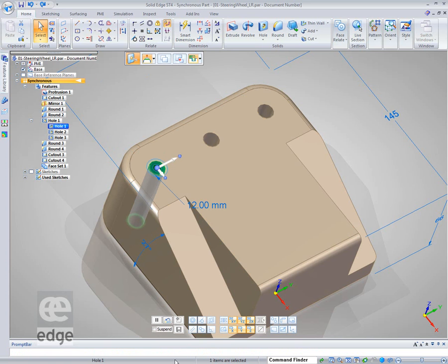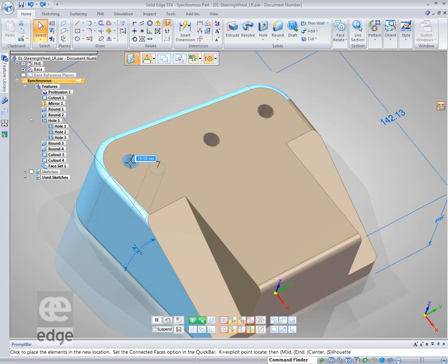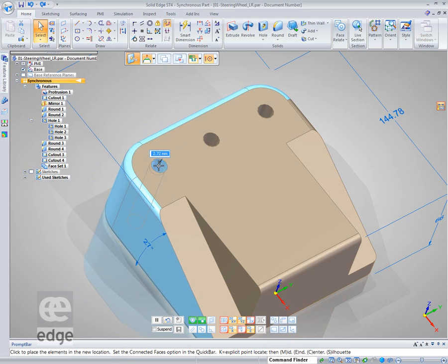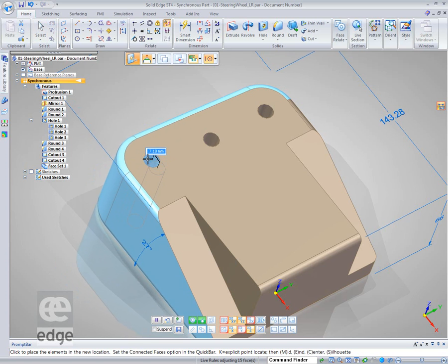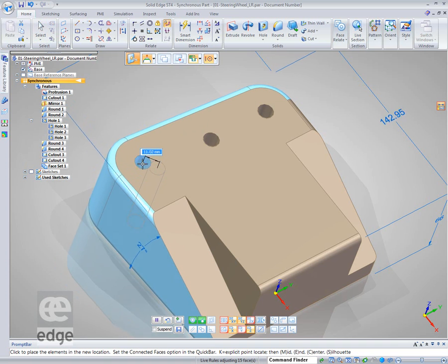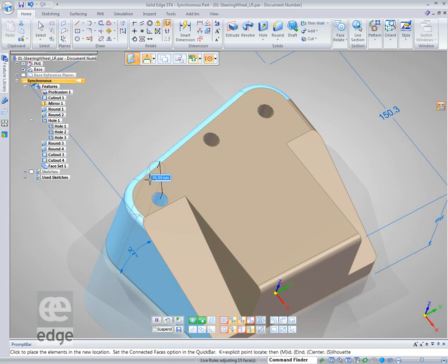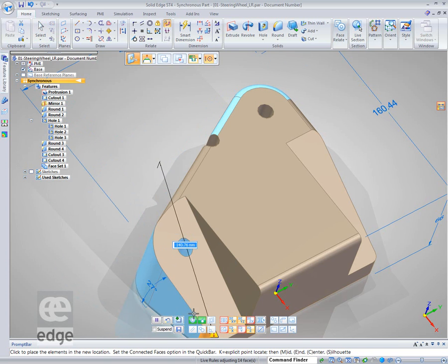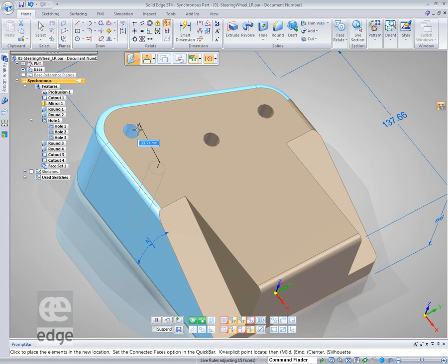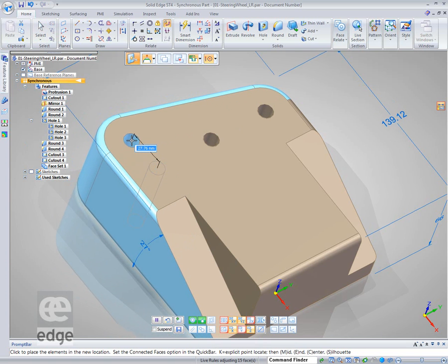Take the rule, but this time I want to turn on concentric and maintain tangent faces. So now when I move this, I'll do the freeform move again. Notice what's happening. The faces that are highlighted in blue are the faces that are being affected. And we can see it's being maintained as concentric. And we can see the tangencies are remaining. If I escape,